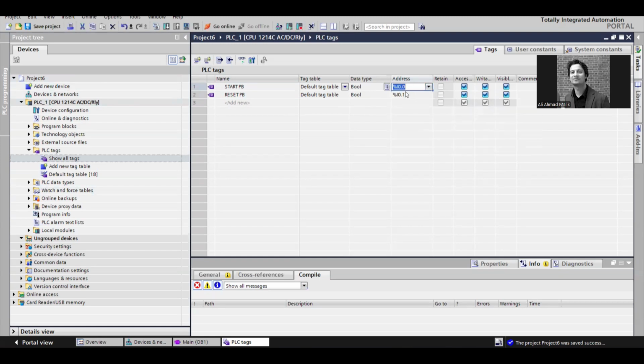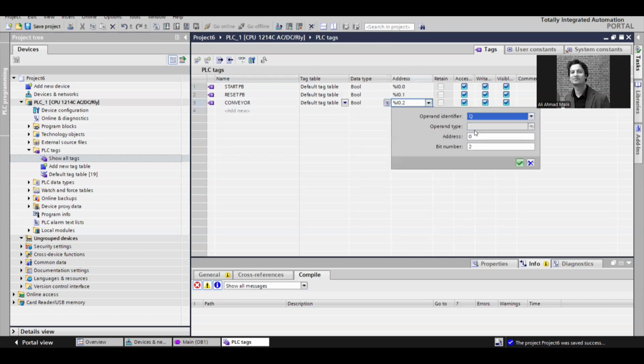So for these ones, I0.0 and I0.1, these are input signals, and then we have 5 output signals, and they are conveyor. It is a good idea to change it to your required one. So if I change it to Q, then all the next ones will automatically be Q signals.